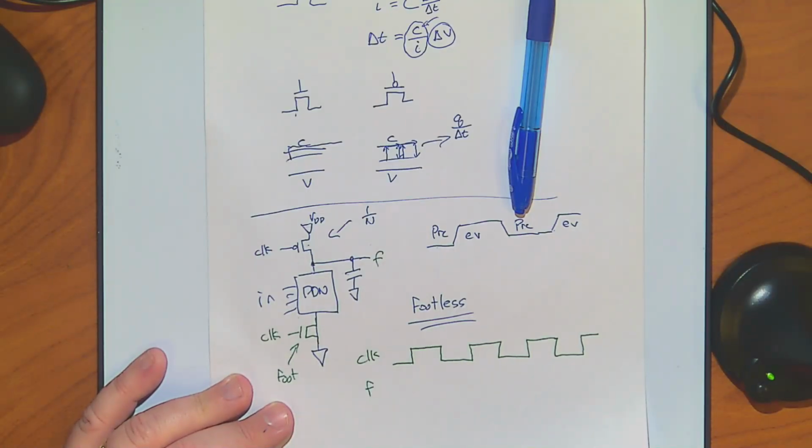But synchronous is also used, if you remember, throughout digital logic design to mean with memory, as well as with a clock. So while it's technically true what they're saying, it's confusing as heck to anybody who's going in there. So it's just better to call it pre-charge, evaluate, or dynamic. And then you should just know, if anybody ever says dynamic, it means the signal's only good at certain times.